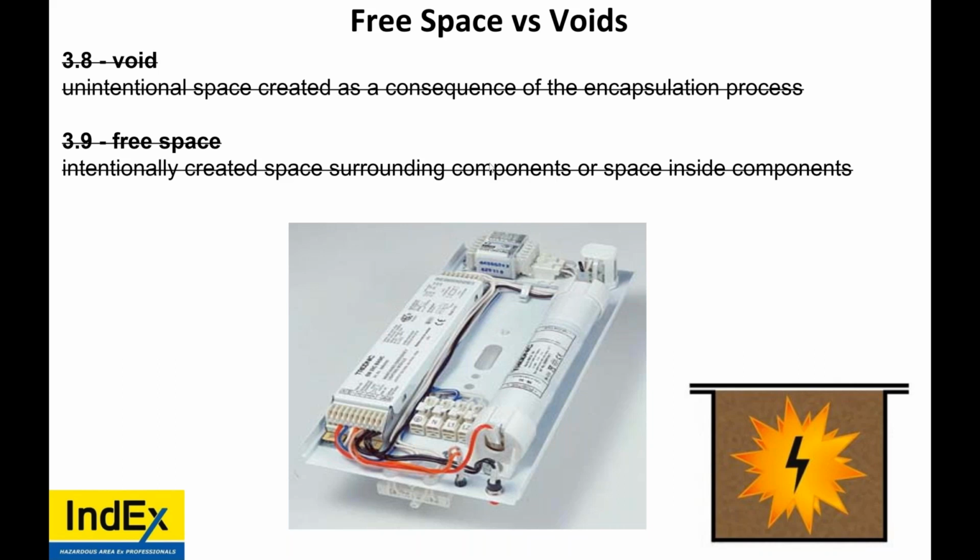EXM product, is it possible to open and do maintenance? The compound is hardened. You do not do maintenance on the compound. You can do maintenance on the enclosure, on the terminations, but no, you do not mess around with the compound. It is hardened, it is permanent. Do not touch it.